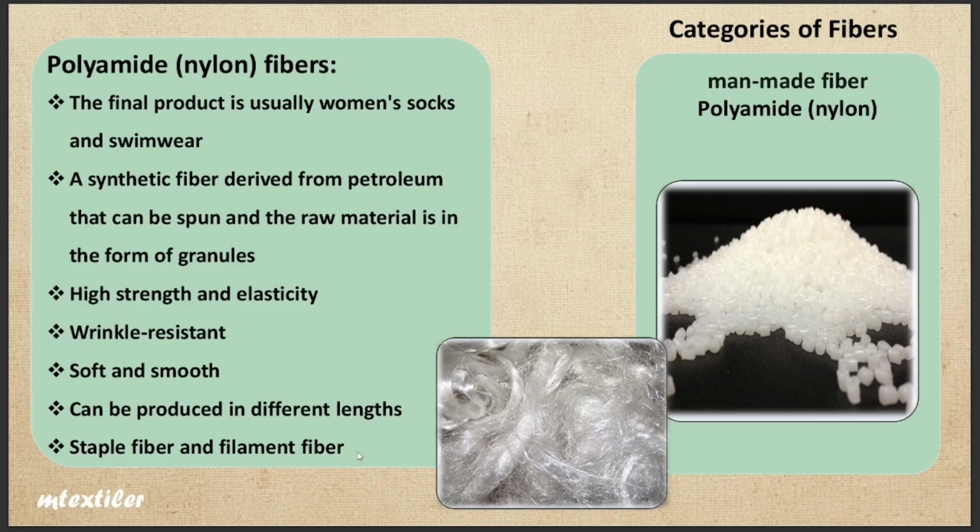Nylon 6 has lower melting point and lower strength, but better dyeability and better moisture absorption because of its lower crystallinity. Nylon 66, due to its higher crystallinity, is generally stronger and is often used for industrial applications.